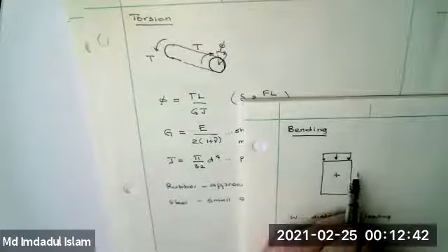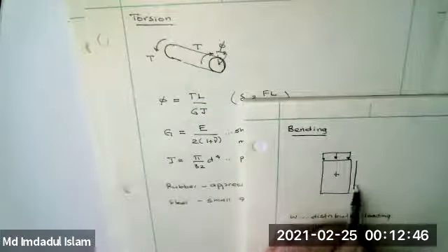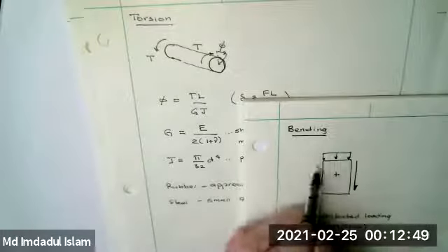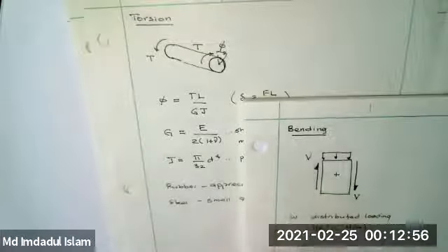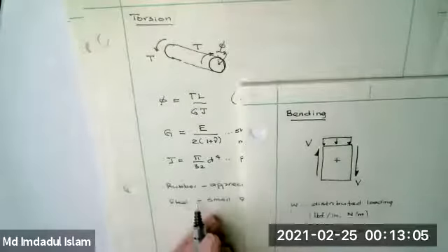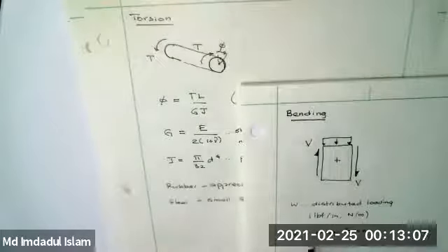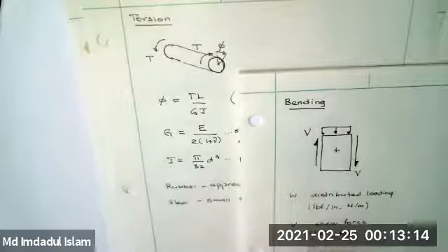And the shear force convention we'll use is the standard civil engineering convention, which is dominant in engineering and MECE to this day. And it would be in pounds force or newtons. And it's positive when producing a clockwise rotation.